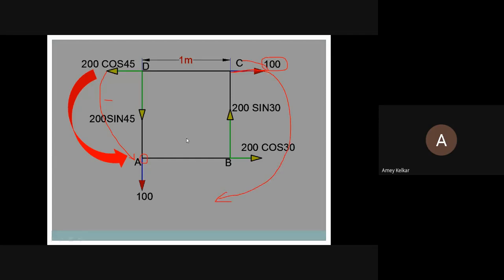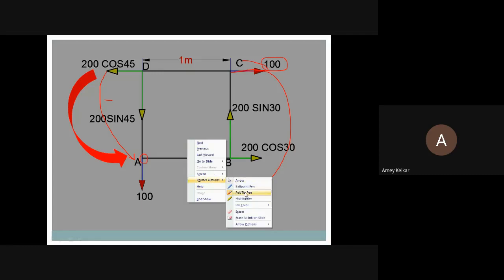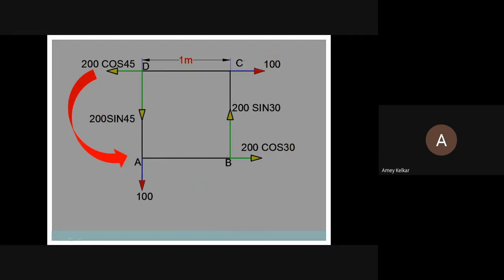Understand this point, because it is not that easy. Move from point C towards the arrowhead. Either the force can turn like this or like this, but I have already come in this direction and cannot go back, as that will not cause a moment. The rotation has to be continuous, so this has to go like this.